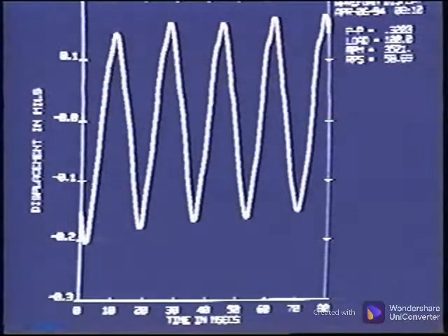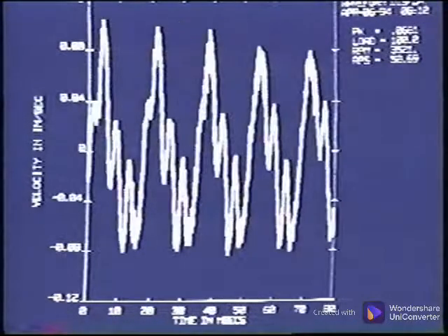This displacement waveform indicates an unbalanced condition in this machine. It is smooth and very sinusoidal, with no other energy apparent. The same measurement point in velocity still has a predominant 1 times sinusoidal waveform, but has other energy that could be multiples of turning speed.